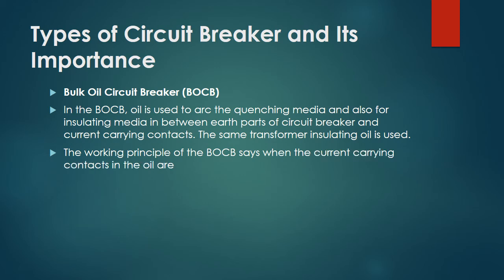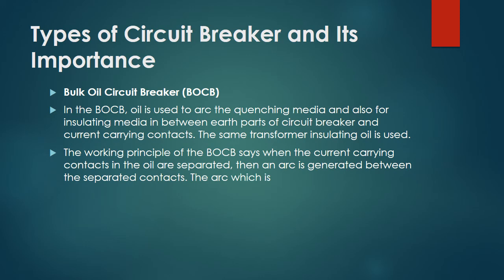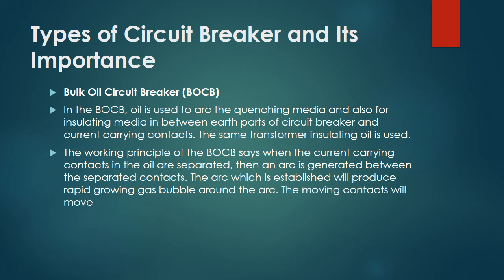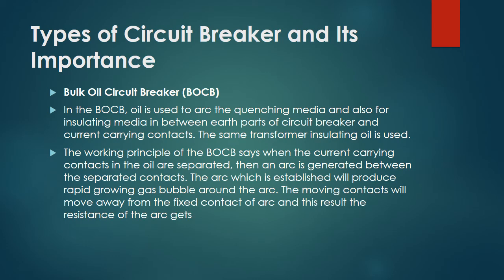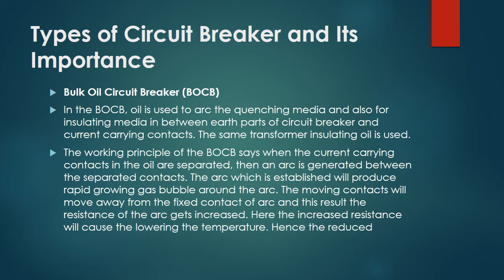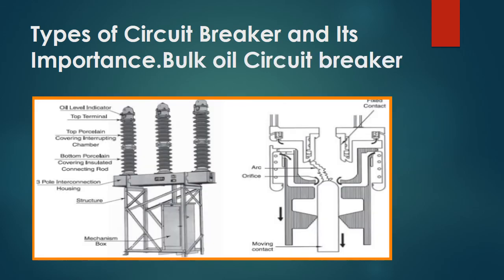Minimum oil circuit breaker. It is a circuit breaker which utilizes oil as the interrupting media. The minimum oil circuit breaker will place the interrupting unit in an insulating chamber at the live potential. But insulating material is available in the interrupting chamber. It requires a smaller amount of oil, so it is called a minimum oil circuit breaker. Requires less maintenance. It is suitable for both automatic operation and manual. It requires smaller space. The cost for breaking capacity in MVA is also less.